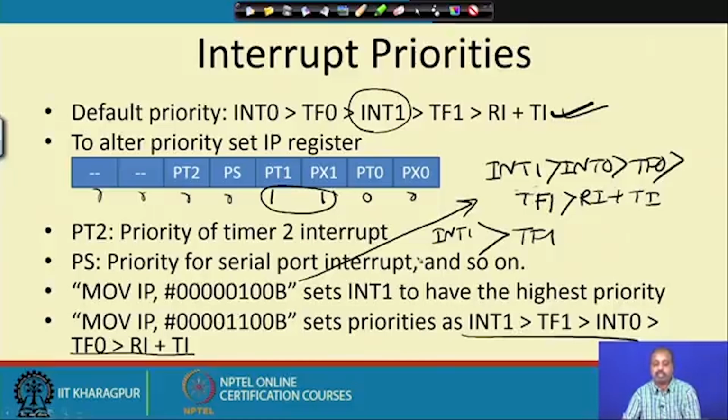Naturally, you can understand that you cannot set these interrupt priorities arbitrarily. Some interrupt combinations are feasible, but you cannot set all of them simultaneously. Still, it is a good option that we can change the default interrupt priorities, particularly because when you are designing a microcontroller based embedded application, you may need to take interrupts from different sources at different times or different phases of the program.